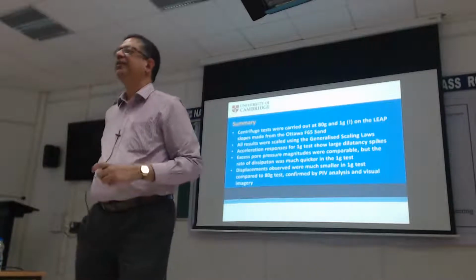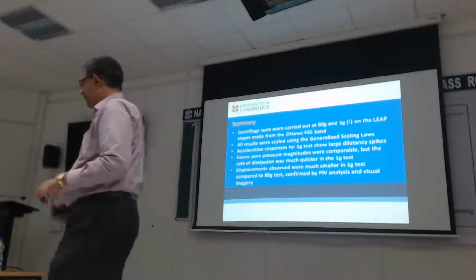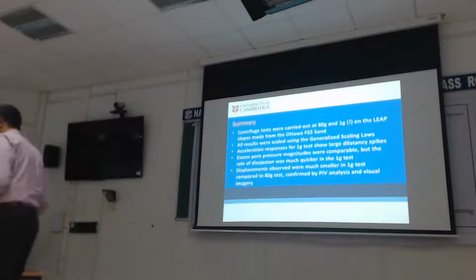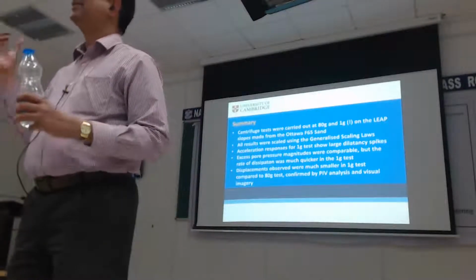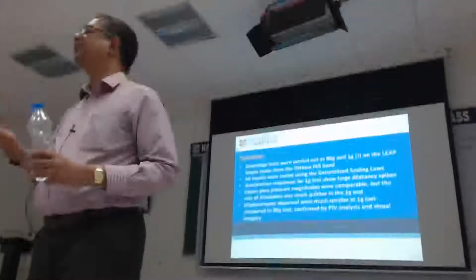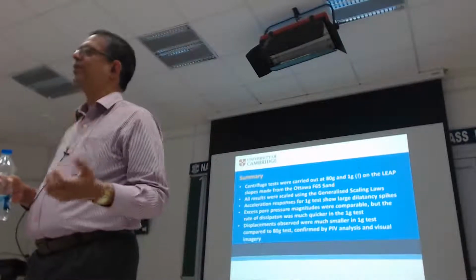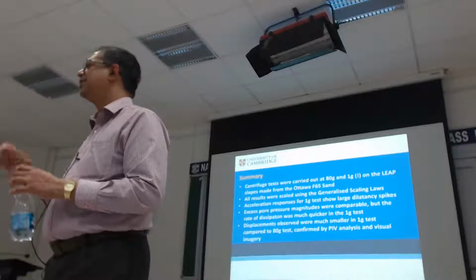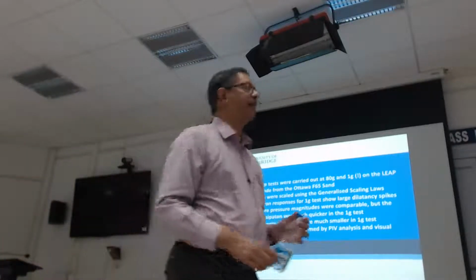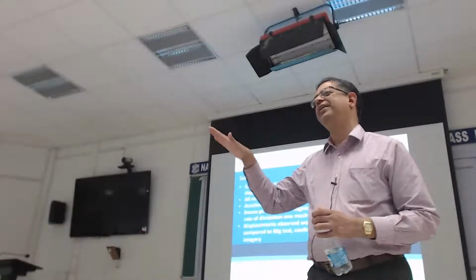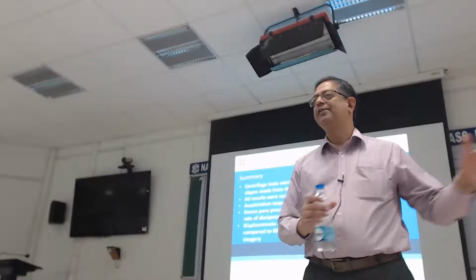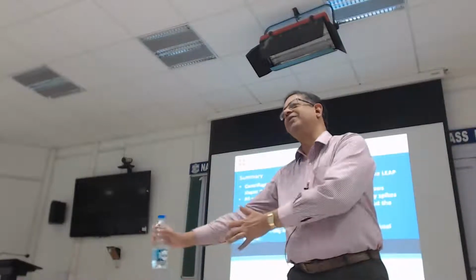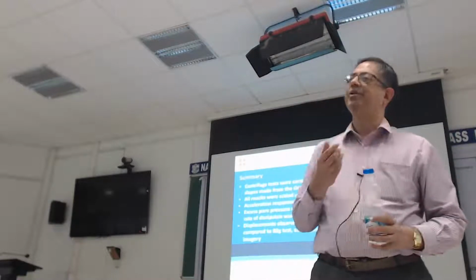Any questions? Yeah? We have tests, the ones I was showing you yesterday with 6 degree slope also. Those are all done in laminar box, and you get a lot more lateral spread. And actually, the mechanism will be right. In this case, we are picking up the failure mechanism as a rotational mechanism, which is not how lateral spreading happens. Lateral spreading happens more like a downward movement of the entire body, and that is captured by the laminar box. And I showed you the displacement